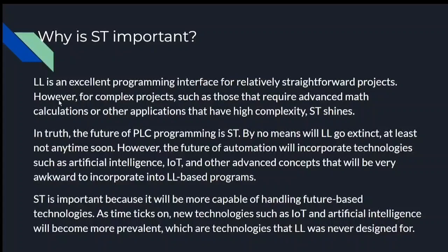When we need to program a motor to turn on and off, ladder logic is nice. It is very easy for simple programming. But for complex projects, we need a language like ST that can be used for advanced math calculations.